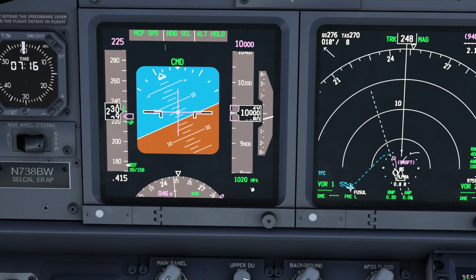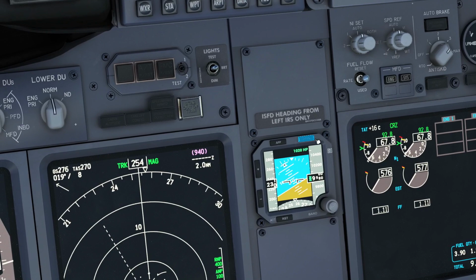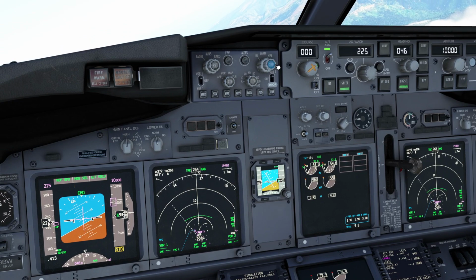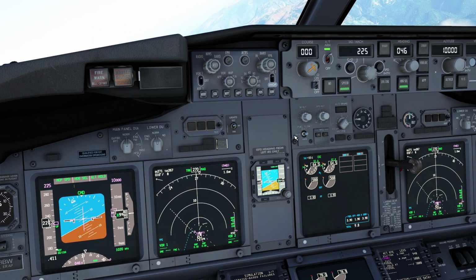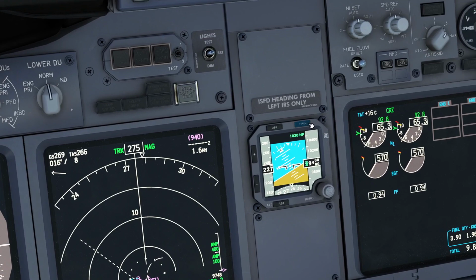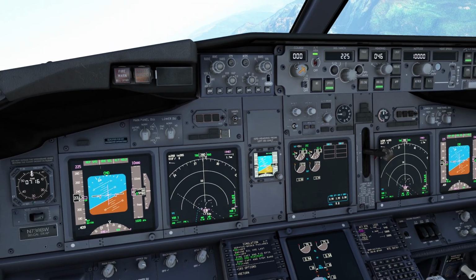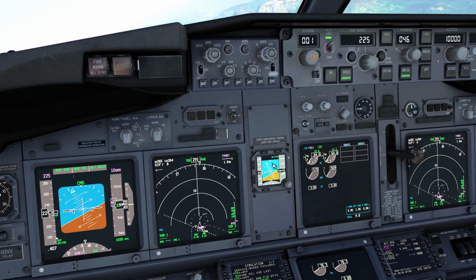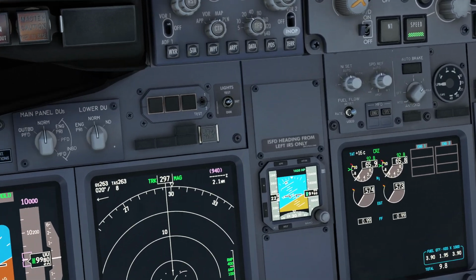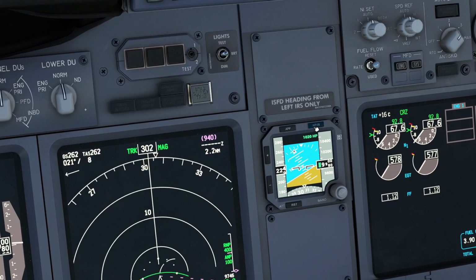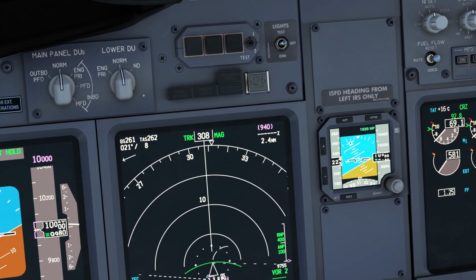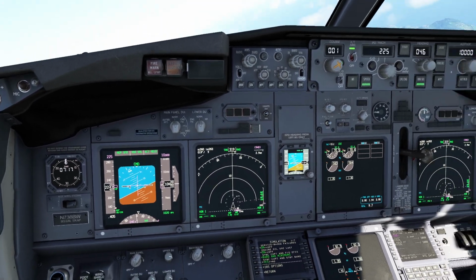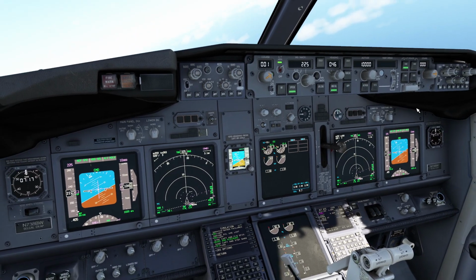So if you are flying in hectopascals, you have to set hectopascals, like 1020, and now anytime you press the standard, it goes to standard, and when you press the standard again, it reverts to 1020, and it will be 1020 here. If you have it in hectopascals, it still does. It's synchronized, but it doesn't change from one to the other. So make sure on your pre-flight you have the same scale, hectopascal or inches, on the standby altimeter and on the captain side.